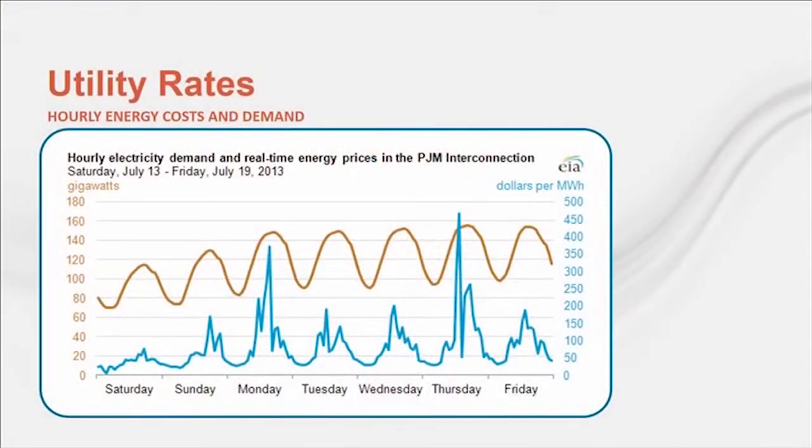As we all know, social responsibility only goes so far in solving problems, but money talks. Early electric meters only measured the energy used between 2 meter readings. As a result, the very first utilities simply charged a flat rate that was the same for all kilowatt hours. It was easy to bill, but not easy to use for behavior modification. The cost of generating power is not constant throughout the day or even throughout the year. It's more expensive to serve a customer that uses all their power in one huge chunk over a short period of time.